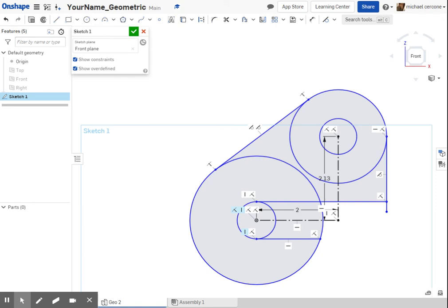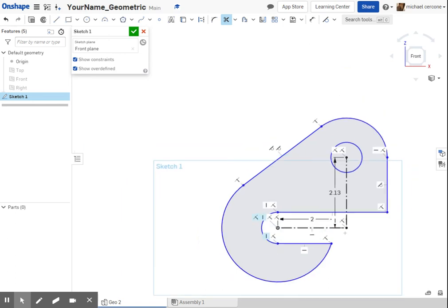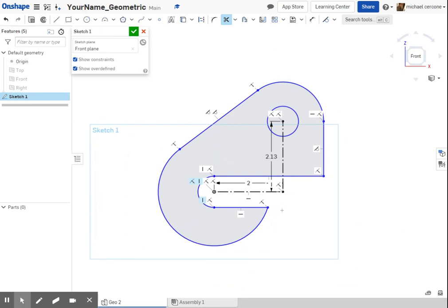Now what I need is just to trim, and then I'm going to apply those dimensions. Selecting the trim tool, trim away this part of the arc, this extension, this piece of the arc that I no longer need. And this looks just like what I was showing you guys before. I'm going to look back at the dimensions. This one is 1 1/2, this is 1 7/8. So I'm going to type D for the dimension tool.